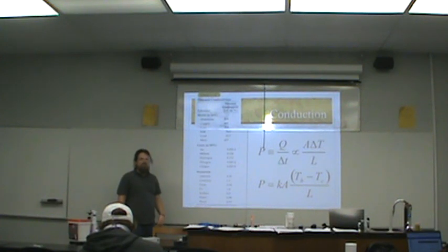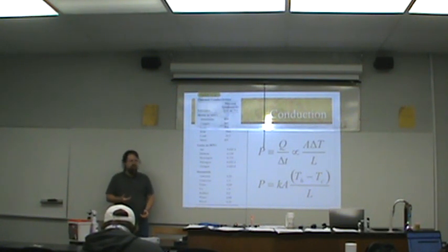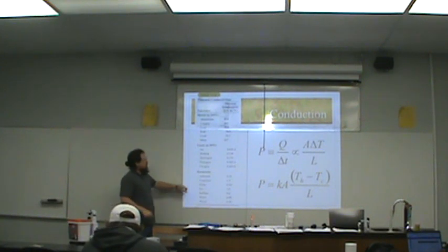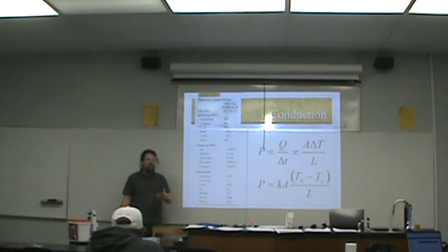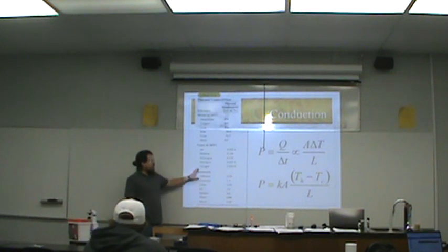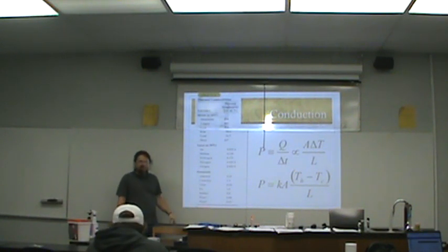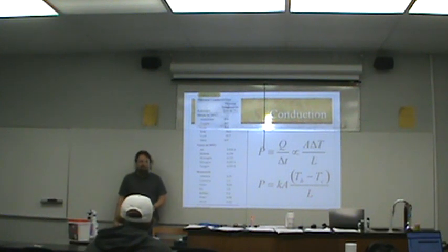So even at the same temperature, they will feel different because, again, you're not sensing temperature, you're just sensing thermal energy passage. And what that means is, these materials, where thermal energy passes through them easily, are good conductors. It's the same word as electrical conductivity. They allow heat to pass through them. They are good at heat moving through them. Meanwhile, these down here are good insulators. They do not let heat pass through them very quickly, so they're good at keeping things on either side of a barrier at the same temperature.